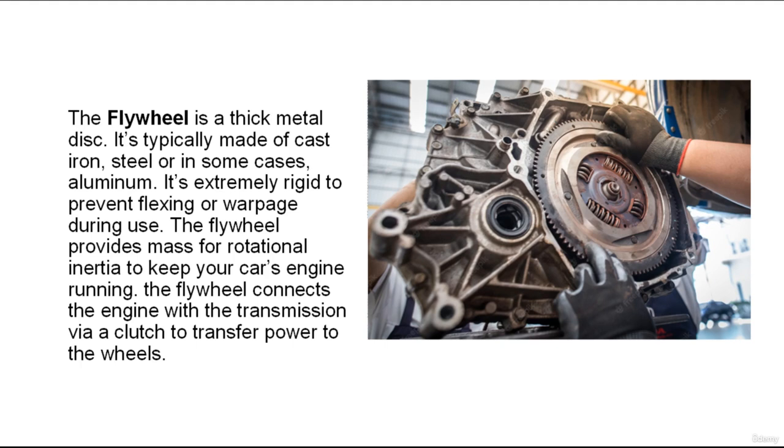Now, the flywheel. The piston is moved by the pressure produced during combustion, but this moves the piston only about half a stroke or a quarter of a revolution of the crankshaft. This explains why a flywheel is needed. The flywheel stores some of the power produced by the engine, and the power is used to keep the pistons in motion during the rest of the four-stroke cycle.